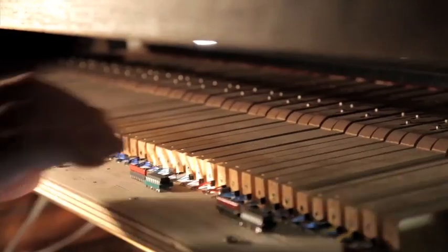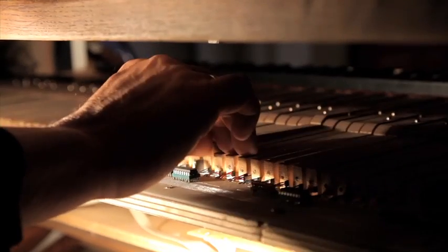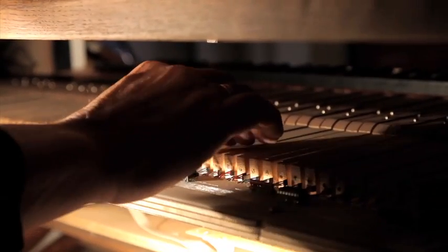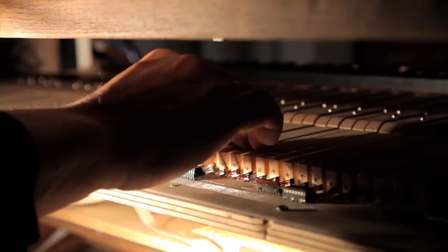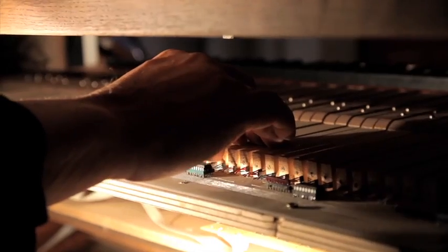Here you have the input boards, which are placed at the rear of the keyboards. Here are sensors, sensitive to magnetic fields, and you have little magnets here. When the magnets are just behind the sensors, the state changes and it sends information to the PC. One can use digital or analog sensors indifferently, and so you can have a sensitive, expressive pipe organ.